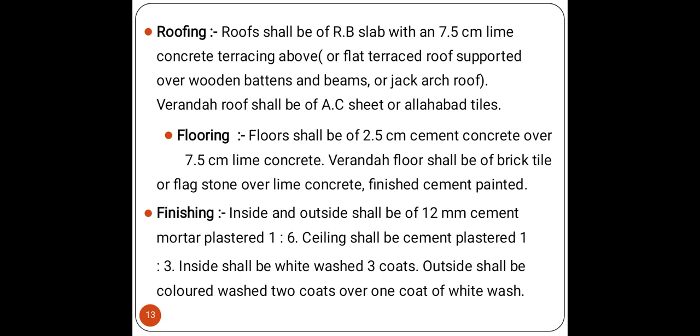Finishing inside and outside shall be of 12 mm cement mortar plaster 1:6. Ceiling shall be cement plastered 1:3. Inside shall be whitewashed 3 coats, and outside shall be color washed 2 coats over 1 coat of whitewash.